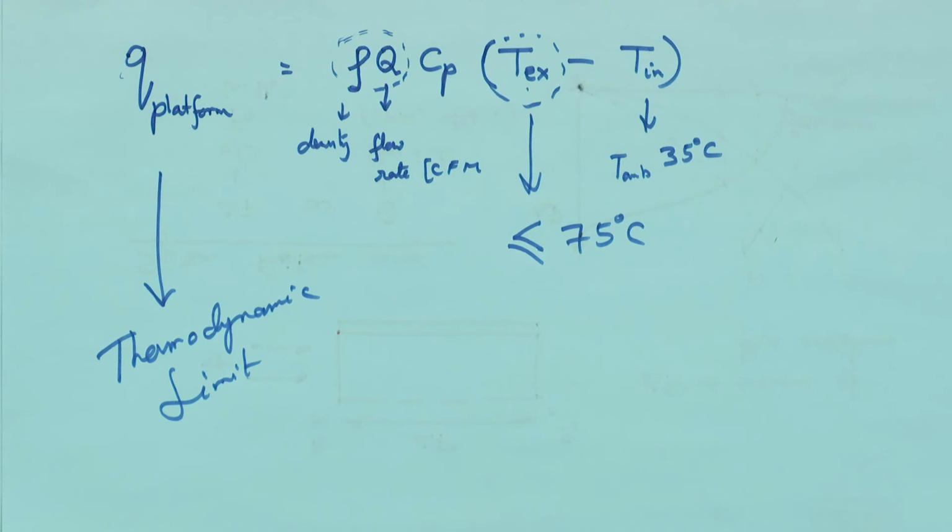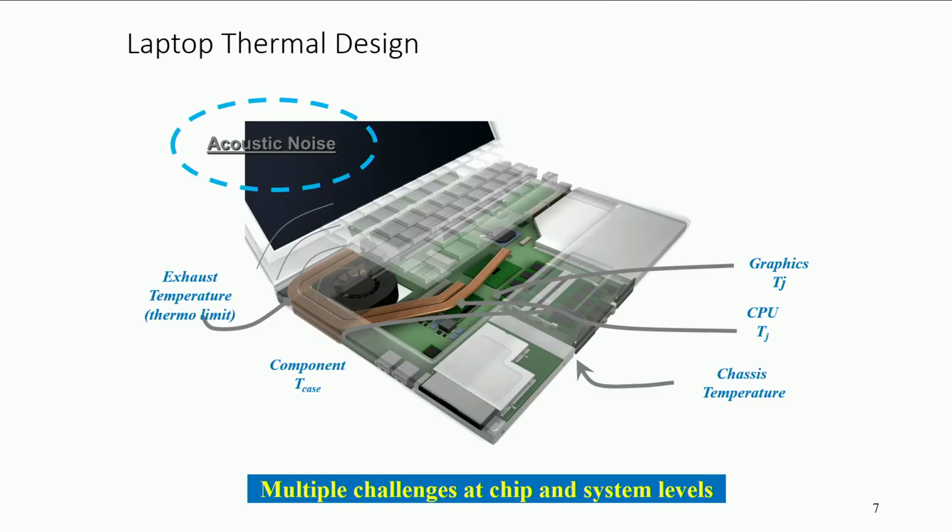Okay. So, just want to mention here a side note. Remember, I was saying that if you are using thermoelectrics or any refrigeration type of system, it is good to extract heat from a certain location, localized heat transfer, but finally what I am rejecting is more than the heat that I am removing, because the external work that I have done either in terms of electrical energy or mechanical energy is converted to heat. So, therefore, for a system that is thermodynamically limited like this, like the equation I have written, if I am already at my thermodynamic limit, I cannot put a refrigeration based system.